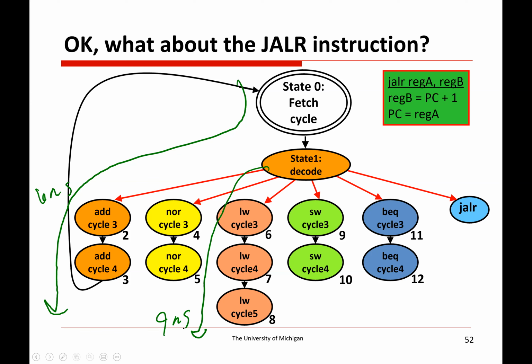So the benefit of doing shorter clock periods and doing more clock cycles is that if each of these is, let's say 2 nanoseconds, so this one takes 3 cycles, and the load word takes 5 cycles. This is great because if we finish the add instruction earlier, we still have to wait to the next clock cycle before we can update anything. But because the clock cycles are happening more frequently, we have more granularity, where instead of waiting the extra 2 cycles after this add instruction, I can say, go ahead and fetch the next instruction. We can start it now because I finished early.